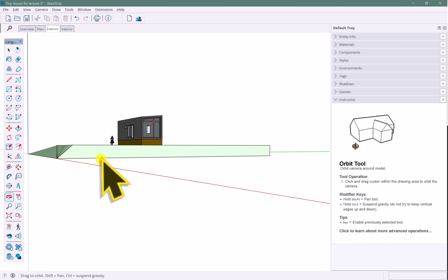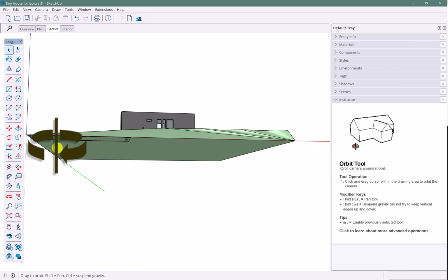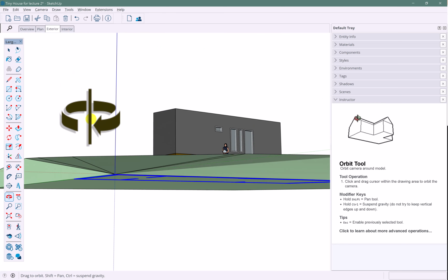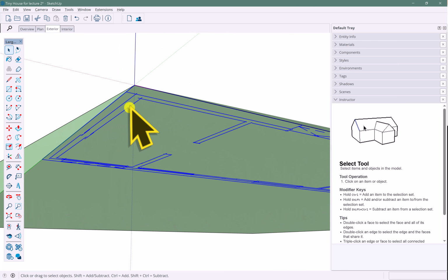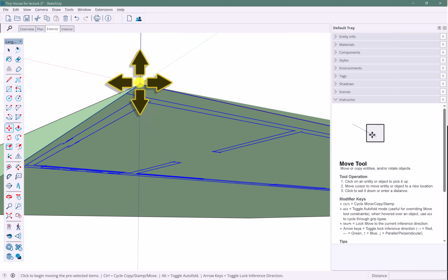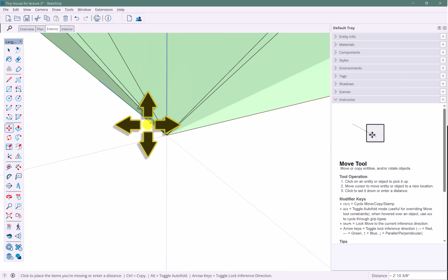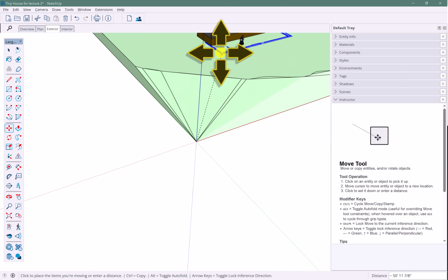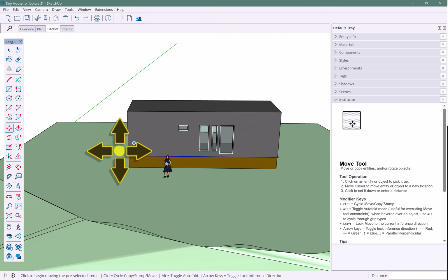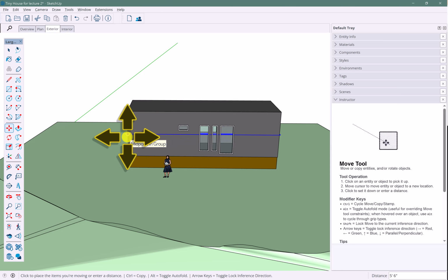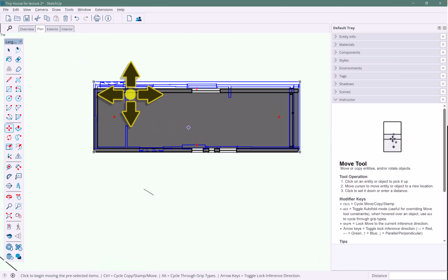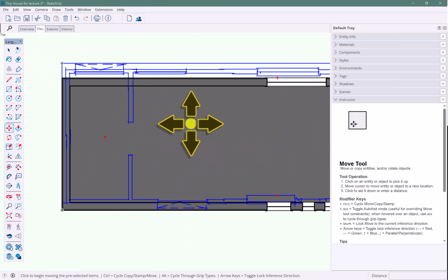Then you have to find it, and you see how it's zoomed out? It's because it imports the CAD file onto the origin. The origin of these files, the 000 location, happens to be right underneath the base of the foundation here, the site. So I can move that by just selecting it. It's an object, and maybe I'll move it over here onto my project. And I probably have to move it up so that I can see it. I believe I made my floor 8 inches thick, so I'll move it up 8 inches. And now when we go to the floor plan, you'll see, oh, there's my CAD plan. And I can move it into position.